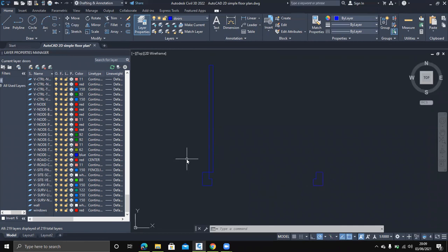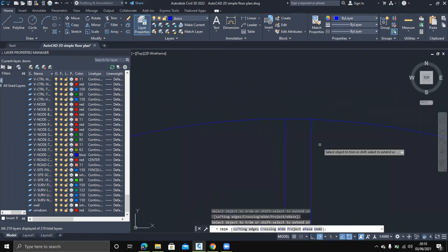So I'll just type Command C, and I will draw some circle from this corner here. And that circle will be at a radius of 800 units, so that I can draw a circle that I'm going to trim this part so that I can draw that door successfully. So once I'm done, I will now revisit the command of trim, and I will start by trimming this end of this circle. There's some end here with a junction. That is the one I will trim first, so that I disconnect that junction, so that this one can now trim as